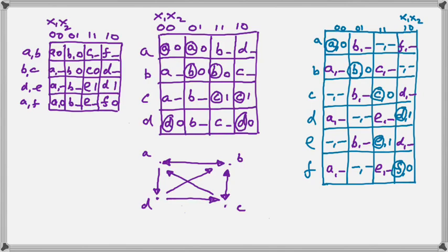The problem with this transition diagram is that it has diagonals. If it was a pure rectangle, we could in fact build the circuit quite easily using 2 flip-flops. But the presence of the diagonals in the rectangle tell us that in fact we are going to need to add an additional flip-flop to make a race-free state assignment.